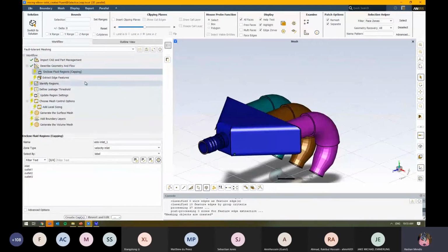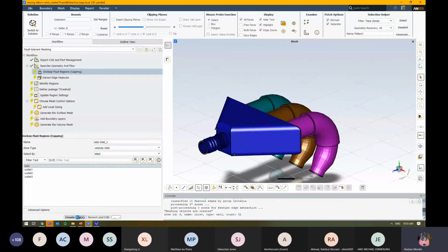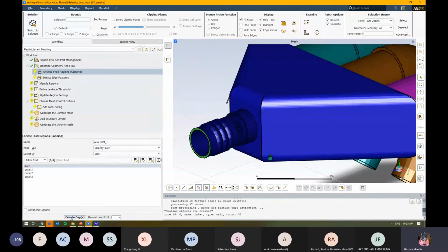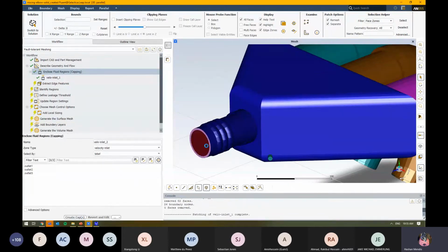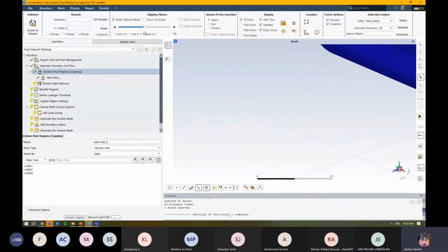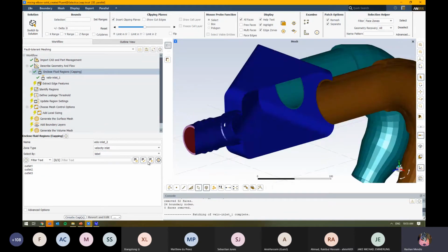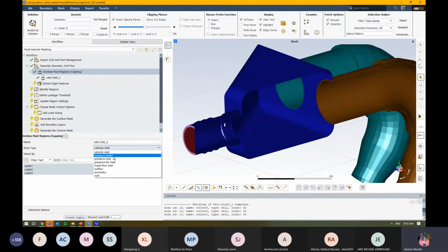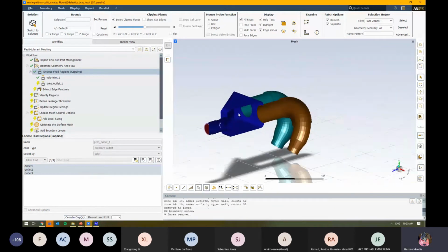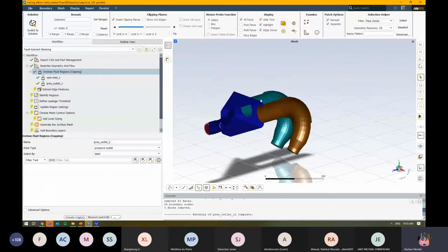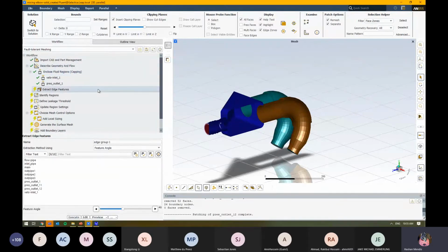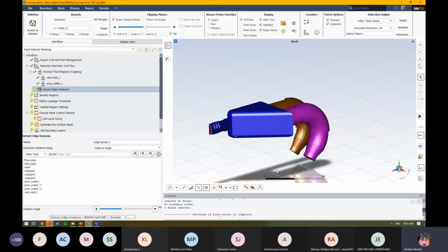So we'll describe the flow. First thing is capping. Again, we've got boundary conditions. All we're doing is telling it this thing here, which we've specified and called an inlet, is actually a velocity inlet, and it will create a cap, right? So you'll see it's actually generated a surface there and capped it off. And then the rest of these ones here are all pressure outlets. Again, the power of this is that if we don't necessarily have the fluid volume extracted, we can actually do that here.